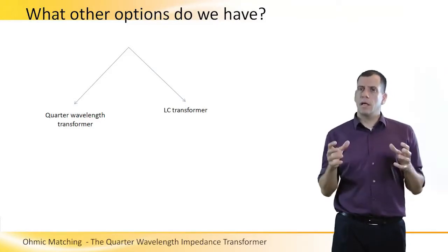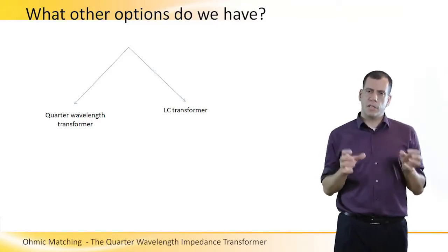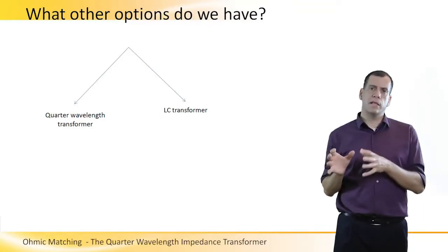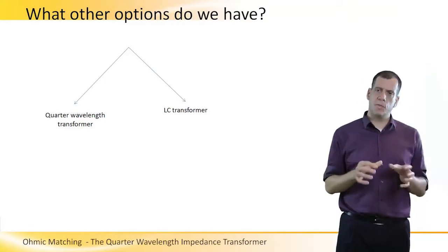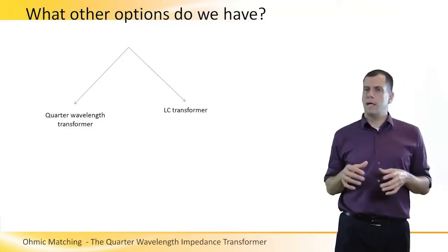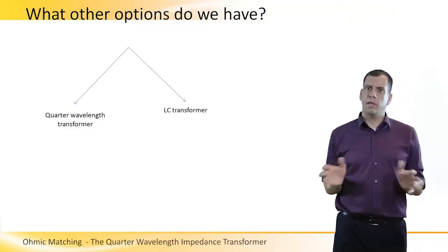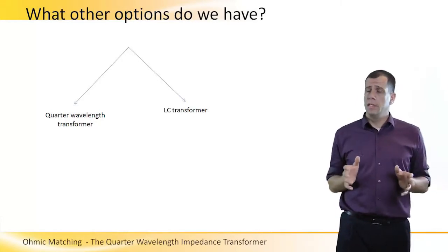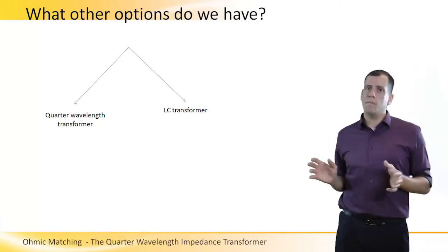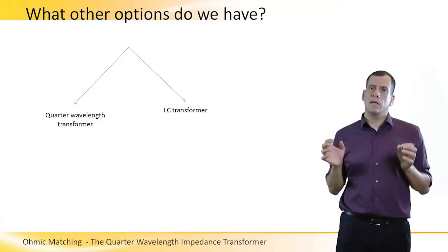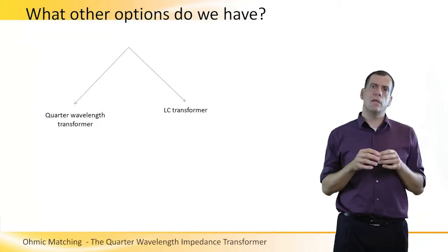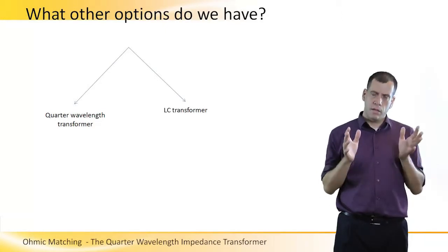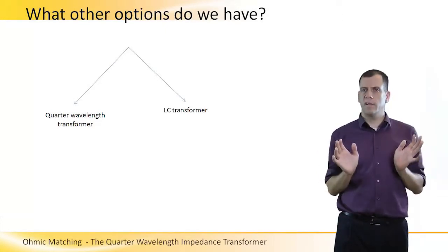Of course, if I'm not mentioning it, then I always relate my seminar to microstrip, which is the most common RF design infrastructure. And when we are talking about microstrip, the quarter wavelength transformer is only a printed line in the length of quarter wavelength.